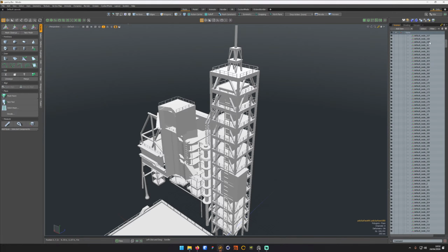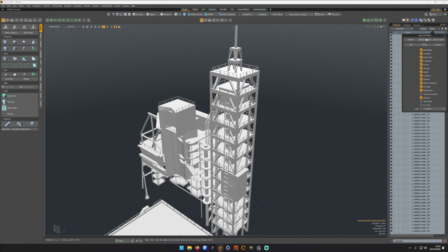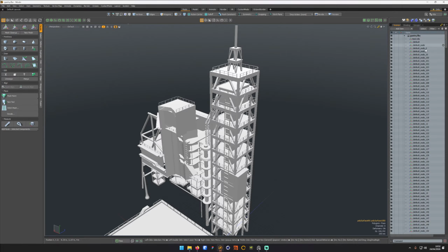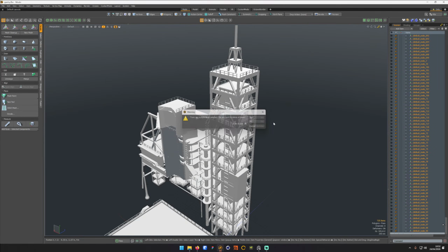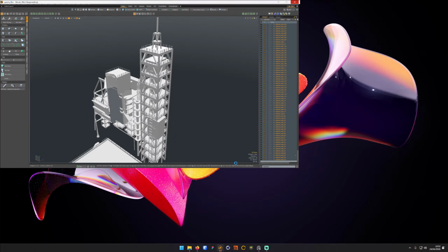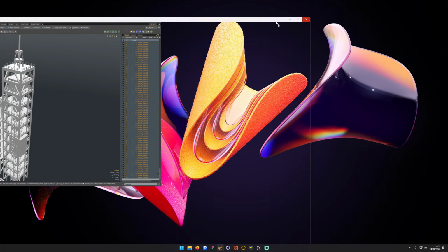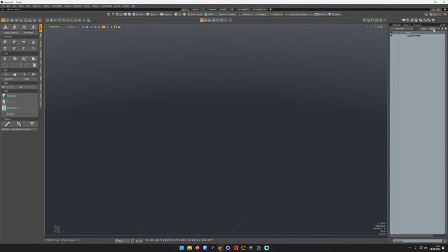So let's just quickly flatten this list, and then we will just do none and just do locators, and we'll get rid of all of those because we don't need any of these locators. This is the one problem of USD stuff, is it makes a lot of noise in the files. Let's get rid of all of them. See if it crashes. It's going to crash. Oh man. Oh, did it? No, it didn't. Oh no, it broke it though. So let's undo that.